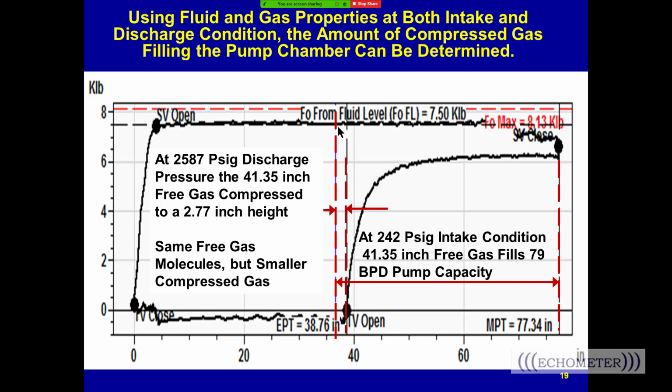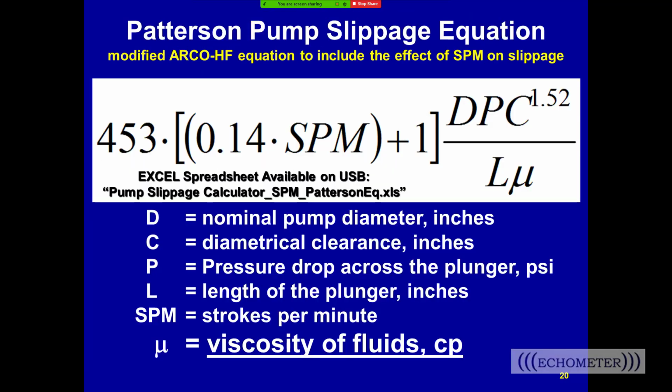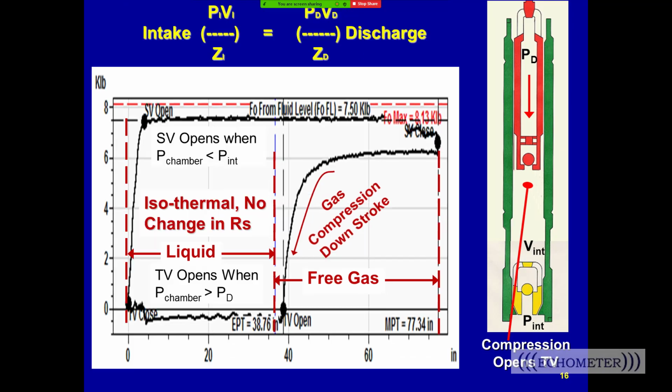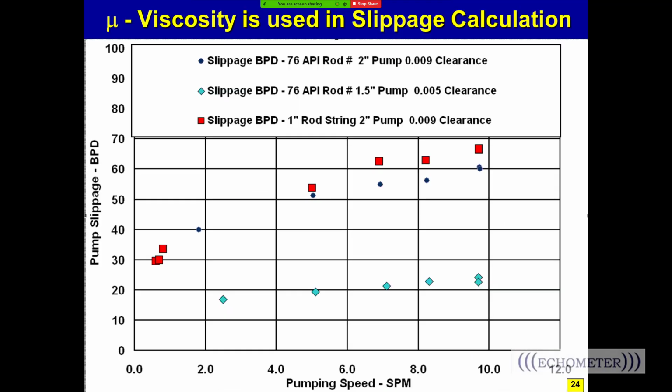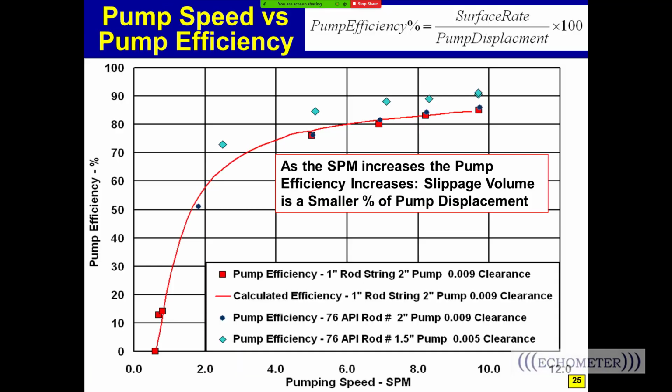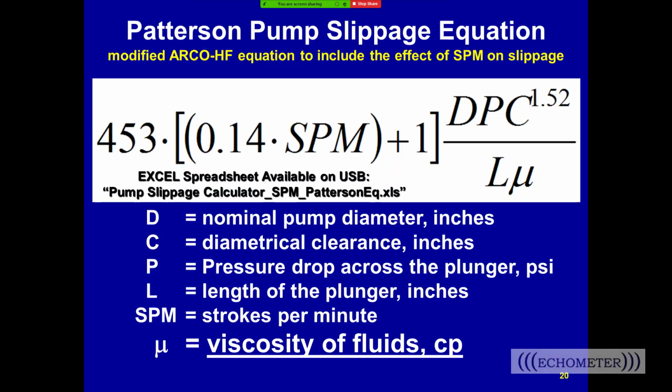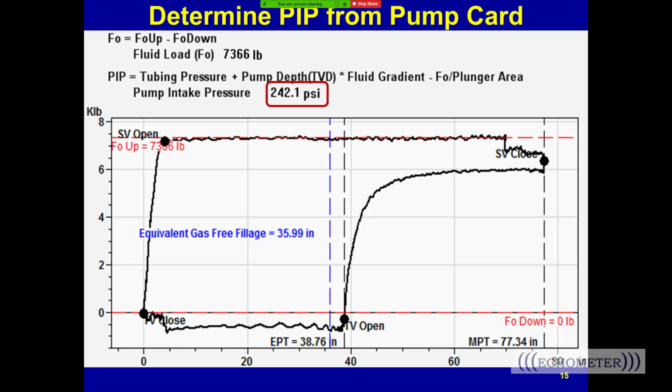So tubing pressure. If we go back to that equation, let me find that equation right here. Where's it at? It's probably before this. So the equation is shown right here. This is the equation. So tubing pressure is important. The deviation survey and the pump depth is important. And the gradient of the fluid inside the tubing is important for the discharge pressure. And that means the production rate, oil and water, need to be typed in and maybe lightened if there's gas going up the tubing.